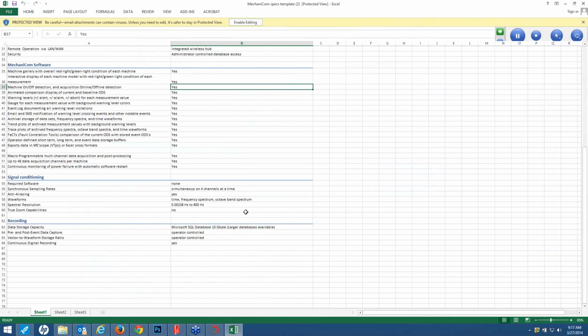Yeah. When you're at an operating frequency in a situation like that, obviously there's a little bit of variability, so the longer you set the acquisition up for, the greater the chance that the operating speed is going to change a hair and you're going to get it a little bit muddied up. But you can set that acquisition up for as long as you want, and the longer you have it on there with a constant operating speed, the higher the resolution you're going to get. You'd be able to zoom in there and get better spectral resolution on both sides. But it's pretty good anyway.